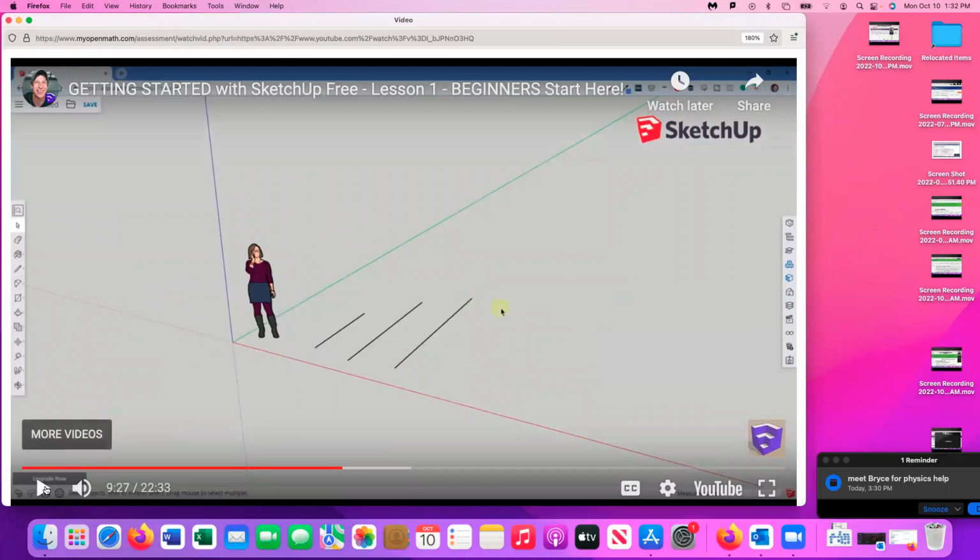What he means by click and drag is don't hold down your button while you're drawing your line. SketchUp is set up with a default that if you just click once, it activates the line drawing tool or whatever tool you're drawing with, and then all you have to do is move your mouse. You don't have to hold the button down while you're moving the mouse. If you do hold the button down, it will still work, but it will not allow you to type in a length. So then you have to get the length exactly right, which turns out to be a pain in the neck when you're dragging around with your finger on the mouse. You end up being off by a 16th or a 32nd of an inch or whatever.